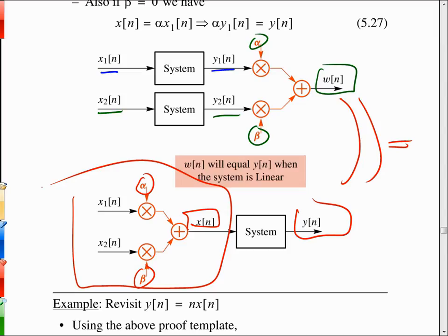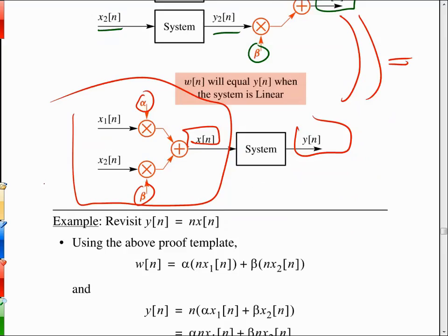So you could back up from there and say, well, that must mean that the FIR filter we started talking about at the beginning of this chapter represents a linear time invariant system as long as it has constant coefficients, or constant b sub k values. And that's absolutely the case. So we kind of avoided some of the mathematical fine points in the beginning so we could get some of the mechanics down, and now we're coming back and looking at some of these properties.